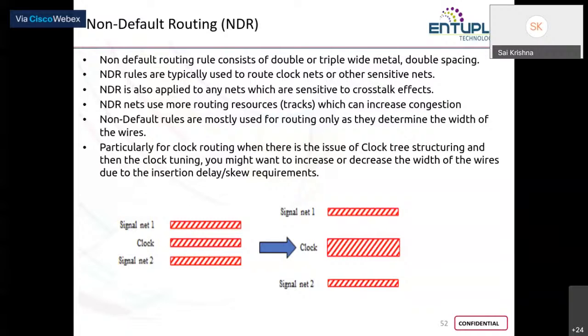And so your signal will try to catch up with your clock, which will form a glitch in between, and could also affect your functionality, because you have a different value from what you expect. So that is how crosstalk happens and signal integrity is affected.